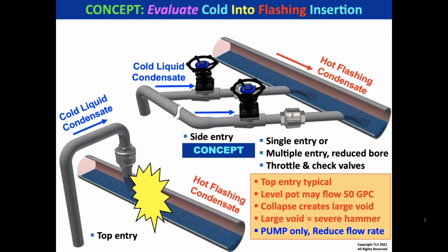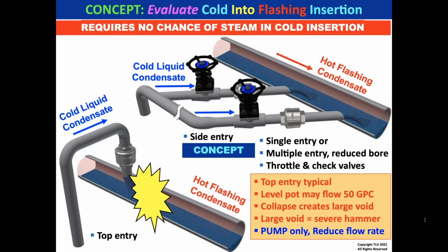In the bottom right, I show that you could only do this with a pumped line only. You cannot do this with any chance of getting steam into it, which means you cannot use it with an outlet control valve steam, because those can blow through steam. And if you blow steam into this header, that would be really bad.